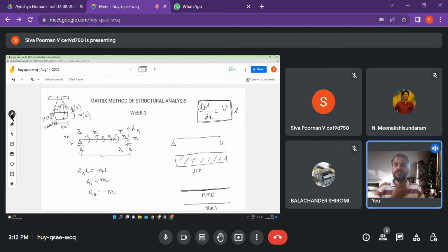So this derivation was based on the assumption that every small portion of the beam is subjected to only forces, not external moments. That's an inherent assumption while deriving this equation. Along with this q of x, actually we should have had plus m of x, a distributed moment. If we would have derived it this way, then we wouldn't have got this formulation. Therefore, this derivation is valid only at places where there are no moments. Since this whole beam is subjected to uniformly distributed moments, this equation is not valid for this beam.